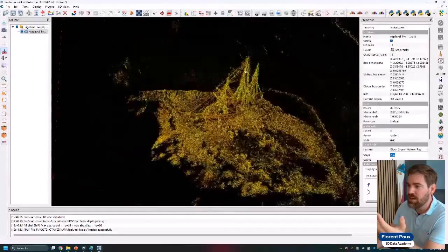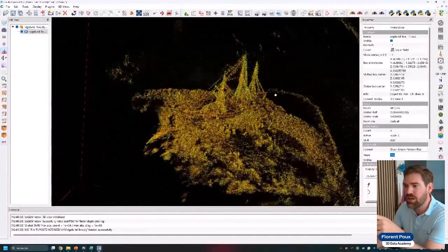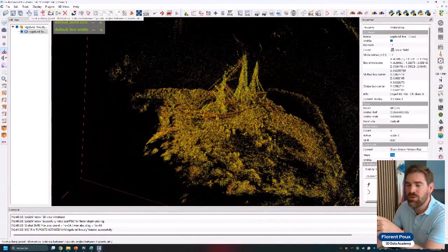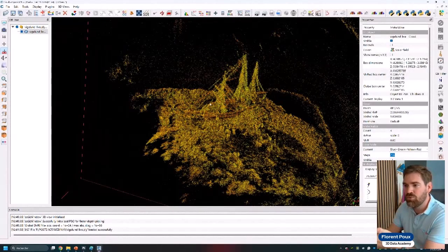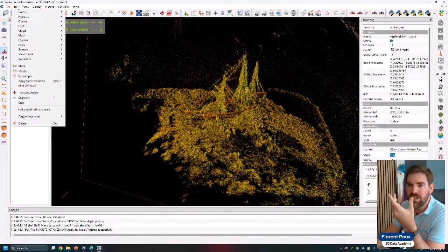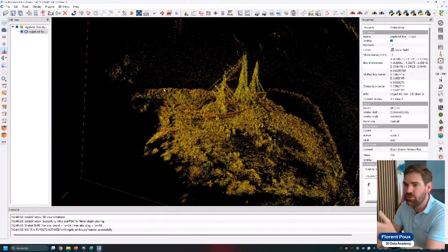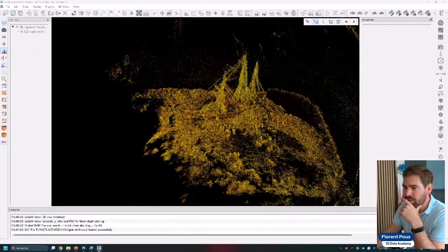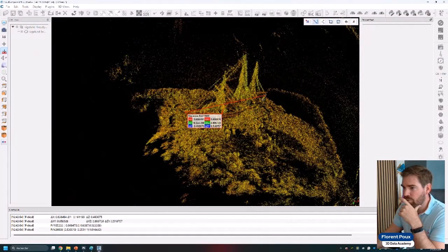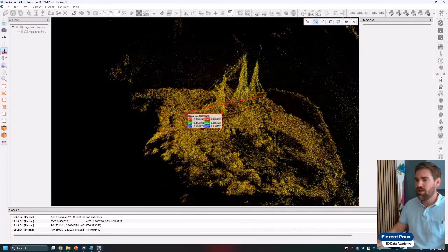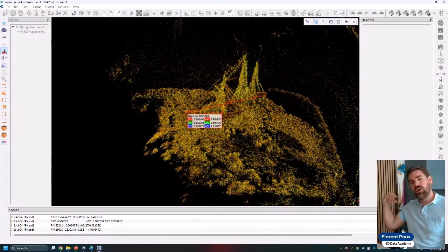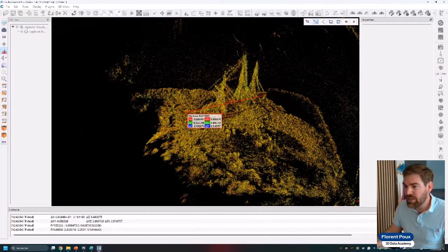And here you get onto classical ways to process the data. If you had a scale, so let's say the scale of this boat is 40 centimeters, basically you could scale your boat to have exactly that. You have ways to scale, so you can scale just by applying a factor, right? So if you want just a factor, you measure. I will take the front of the boat and the back of the boat. Here it says that it's 82 centimeters, which may actually well be the case, but that will be pure luck. It's not at all based on the camera poses estimation, because we had no clue or no scale information. So we cannot extract that directly.